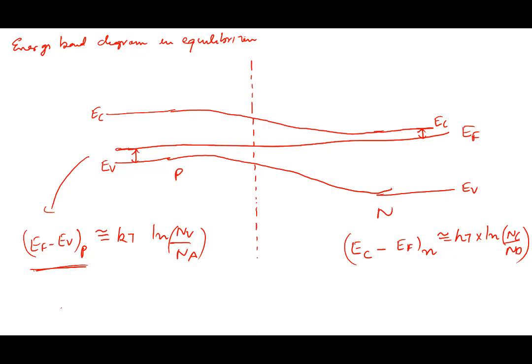All right. So this diagram now, what information do we get? Why do we keep on drawing this band diagram? As I said, any discussion of a new semiconductor device begins with drawing a band diagram, which is like qualitatively solving the Poisson's equation. What do I get from here? Suppose right now we constructed a band diagram for a PN junction, fine. But suppose I were to give you a band diagram like this and ask what information you can deduce from it.